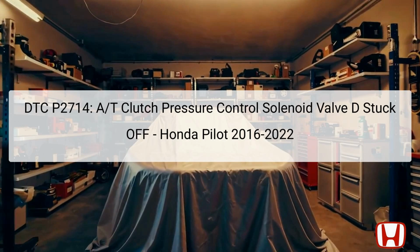The DTC P2714 is related to the automatic transmission's clutch pressure control solenoid valve D, which is responsible for regulating the hydraulic pressure applied to the clutch components of the transmission. This error indicates that the solenoid valve D is stuck in the off position, which can lead to poor shifting